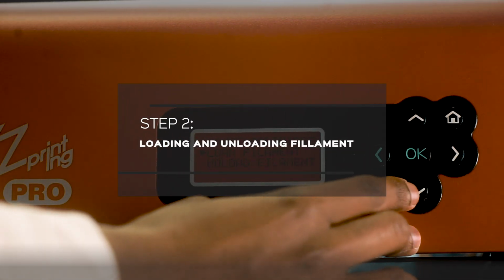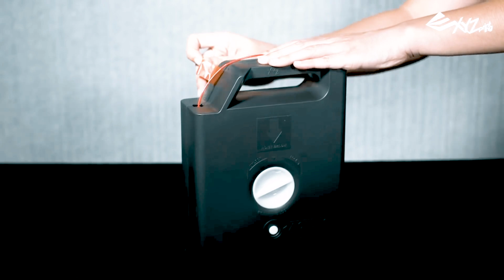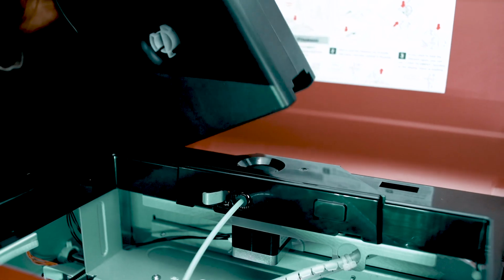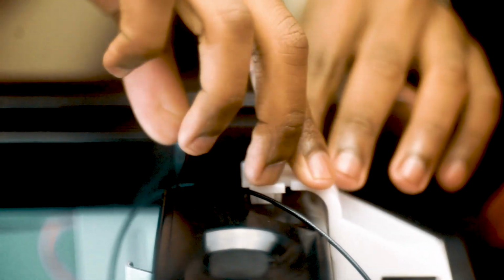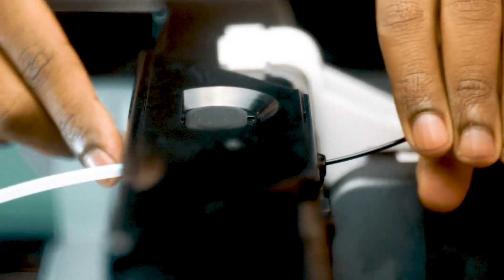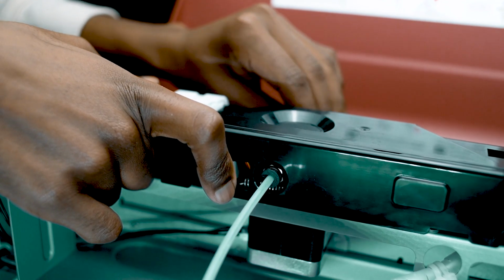Step 2. Loading and unloading filament. Remove the filament stopper tape and load the filament. Place the cartridge into the filament slot. Use the cartridge locker to secure the filament. Insert the filament into the filament hole and make sure that it's in all the way.